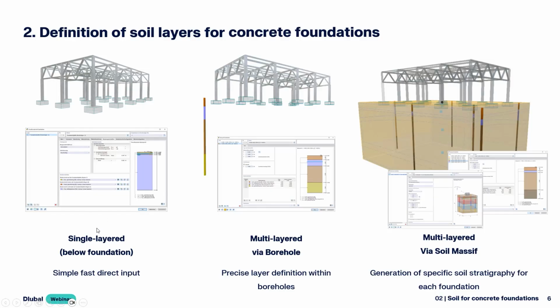We have the type single layered, where you can define the soil layers directly in the dialog for the foundation, relatively simple and quick, and yeah, this is a fast way of direct input of the soil situation. If you have a layered soil below the foundation and you want to consider this and define it, we provide the option to use the borehole dialog.